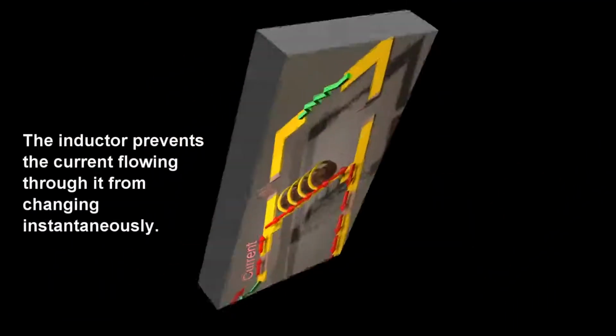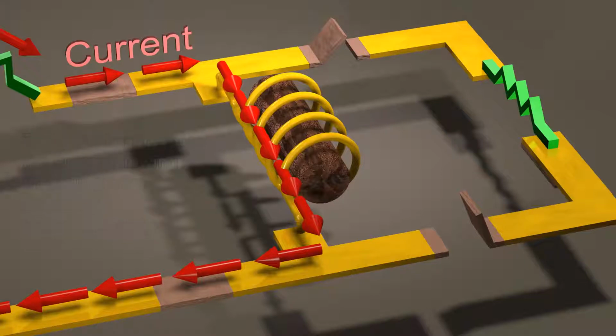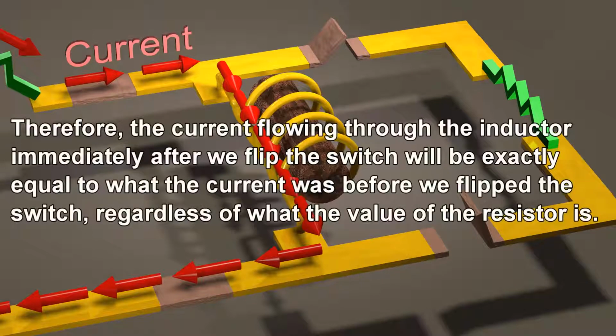The inductor prevents the current flowing through it from changing instantaneously. Therefore, the current flowing through the inductor immediately after we flip the switch will be exactly equal to what the current was before we flip the switch, regardless of what the value of the resistor is.